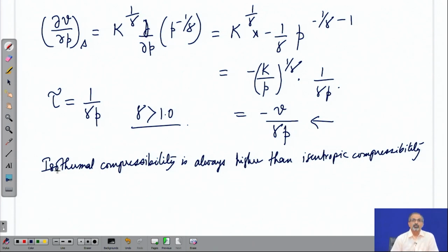Okay. So, whether isothermal or isentropic, if the pressure changes are considerable, then there will be significant changes in density, and therefore, what finally matters is the density change. A few percent change, typically restricted to about 1 or 2%, may be ignored, and then we can consider that kind of situation as incompressible.